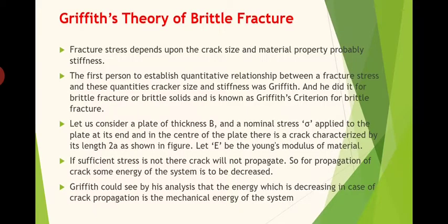Okay. Now, anyway, the basic idea is that propagation of the crack is what creates the fracture, that is sure. But for anything to propagate, some energy is required. So, some energy of the system is to be decreased for the propagation of the crack. So, Griffith thought about what that energy would be which is getting decreased. We know that some form of energy is to be decreased for another form of energy to increase. So here the crack propagation is taking place through the material. So for the propagation of that crack we require some energy.